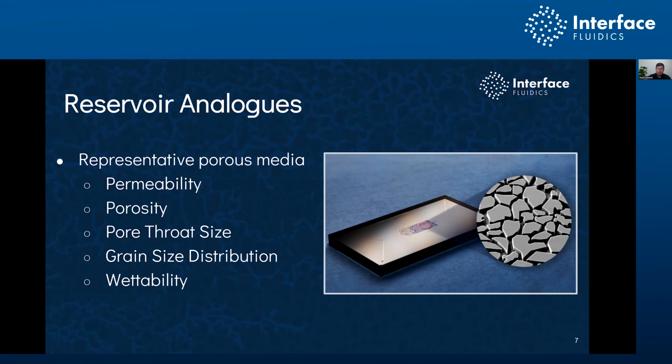If they're in a sandstone, looking at sand grain size distribution. If they're in sort of non-sandstone systems, we'll take thin sections and look at sort of morphology of pores and pore throats, as well as recreating the wettability. And so the goal of this is to create a porous media that is representative of our client's system so that when the fluids are in there interacting, they're behaving as they would in the field.